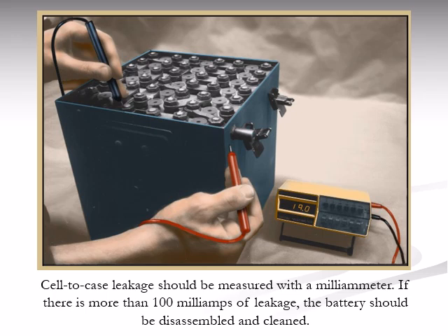If the leakage exceeds this limit, the battery must be disassembled and thoroughly cleaned. Proper cleaning and reassembly help restore insulation and ensure the battery operates safely and efficiently. Routine leakage testing is a vital part of NiCad battery maintenance and should never be overlooked.